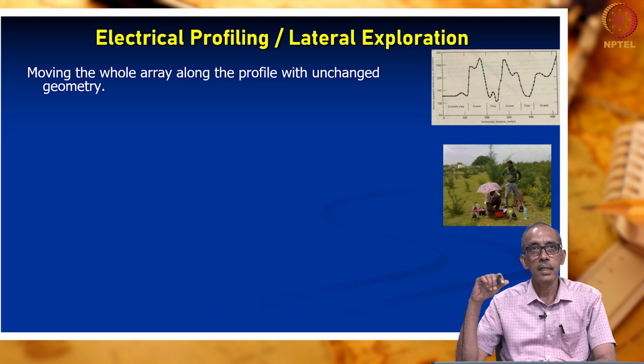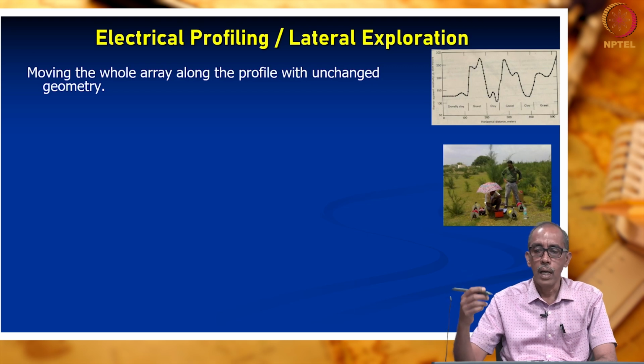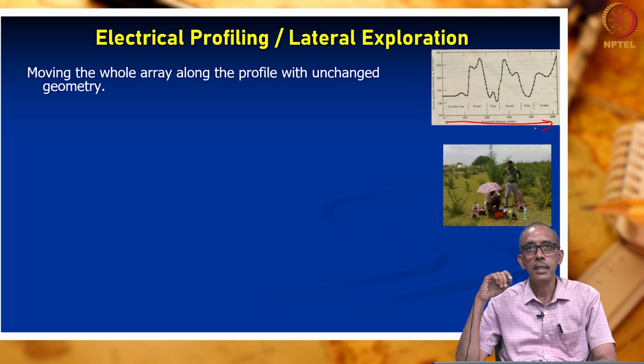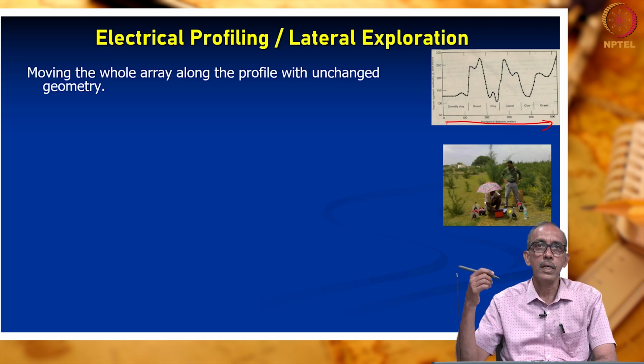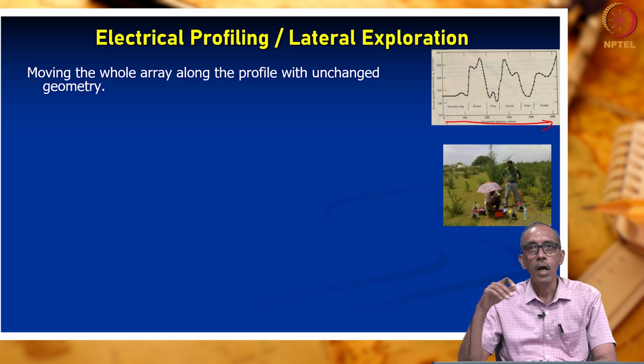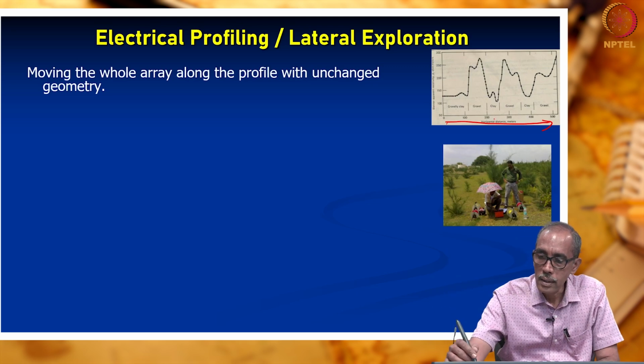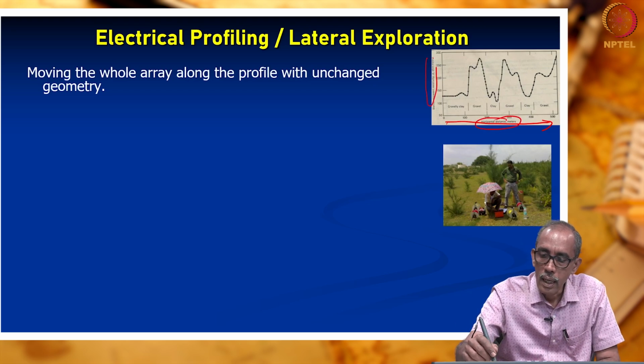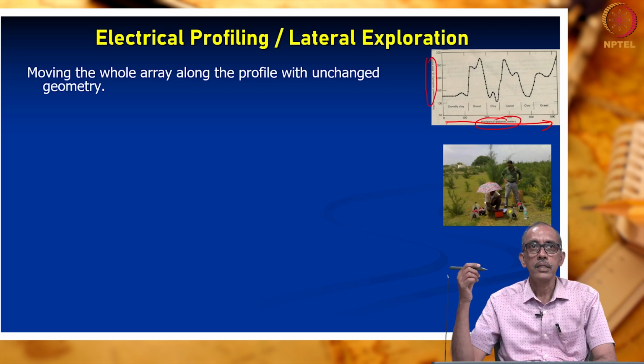First, let us take up electrical profiling. So, what is electrical profiling? In electrical profiling, our aim is to understand the variation in the type of rocks, the characteristics of the rocks below the surface along a particular profile. So, the x-axis here is the distance and the y-axis is the apparent resistivity. How can we achieve this?